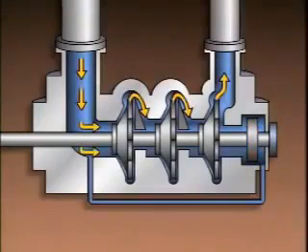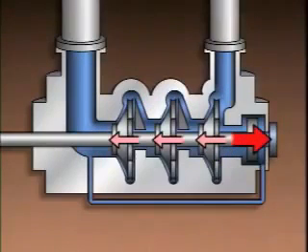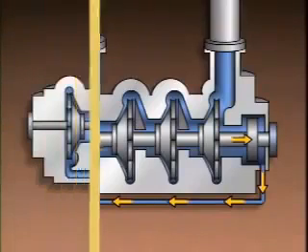During operation, some of the fluid leaving the pump flows along the shaft and exerts pressure against the balance piston. That pressure tends to force the pump shaft away from the suction eyes and reduces the total thrust. Any fluid that passes by the balance piston is returned to the suction side of the first stage.